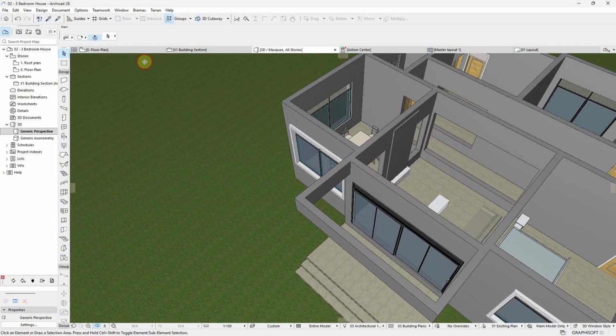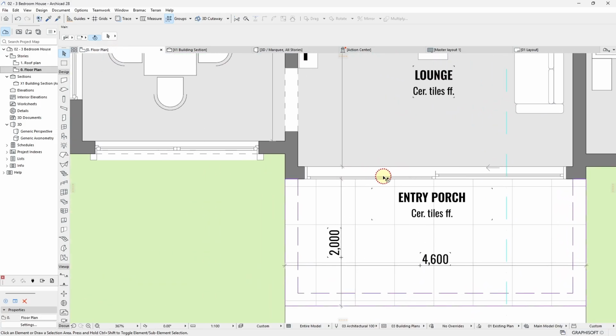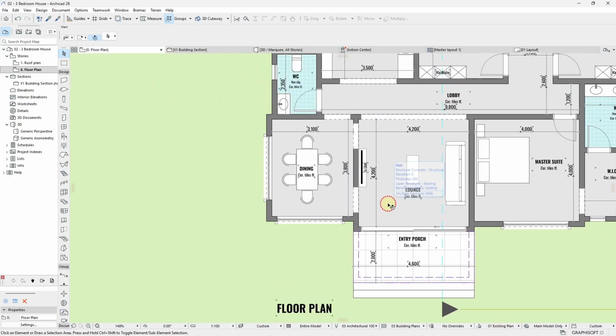Now I want to come and put a roof on this particular part here. And as you're designing, your brain is always at work, constantly thinking: if I put this roof here, where will I drain this roof? Because flat roof houses have that issue of drainage. So in this particular situation, what I did with my design was I had to drain my roof this way. I'm going to show you.